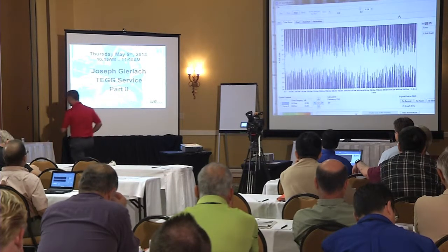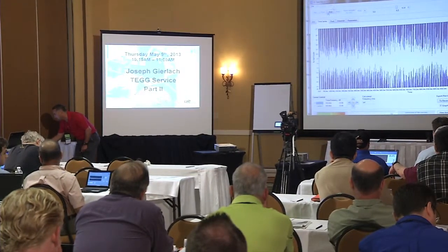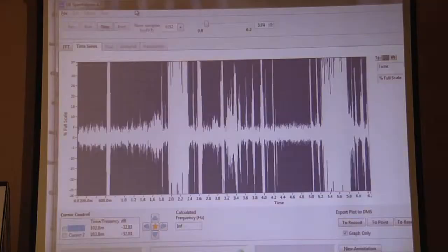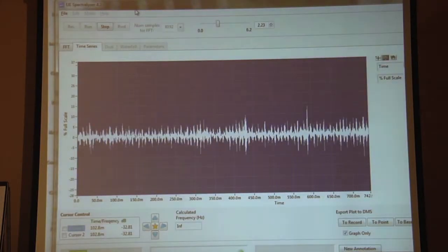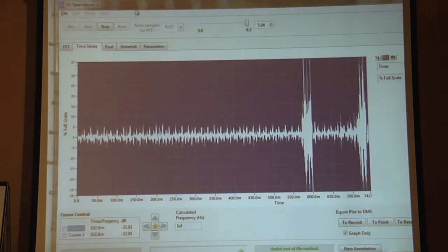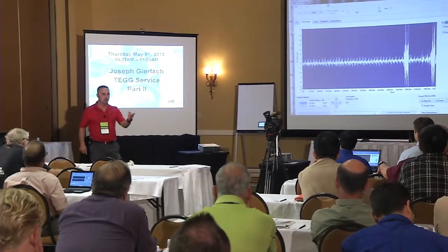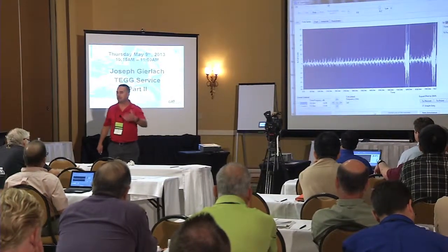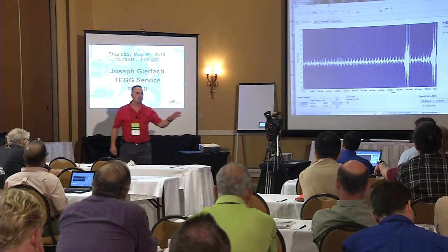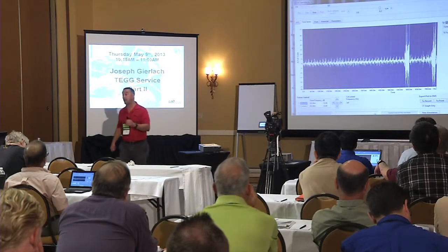Arcing is a little bit different. If I play the arcing wave file here, we have a totally different time spectrum. Now, if I was to characterize that based on what I heard, what would I say? Well, I've got these really intense discharges that are taking place, but then there's times where it's totally silent, right? So I can visualize that on a time and amplitude base.